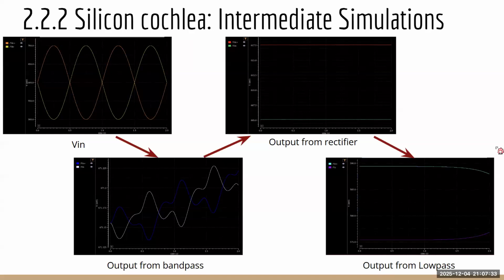And so here's some of the results of testing the silicon cochlea in particular. It wasn't working with the natural heart signal that we were simulating for a number of reasons. Namely, the first one being that the natural heart signal actually passes outside of our rails, and so the signal would start to get clipped there. And it's also comprised of multiple different base fundamental frequencies and harmonics.